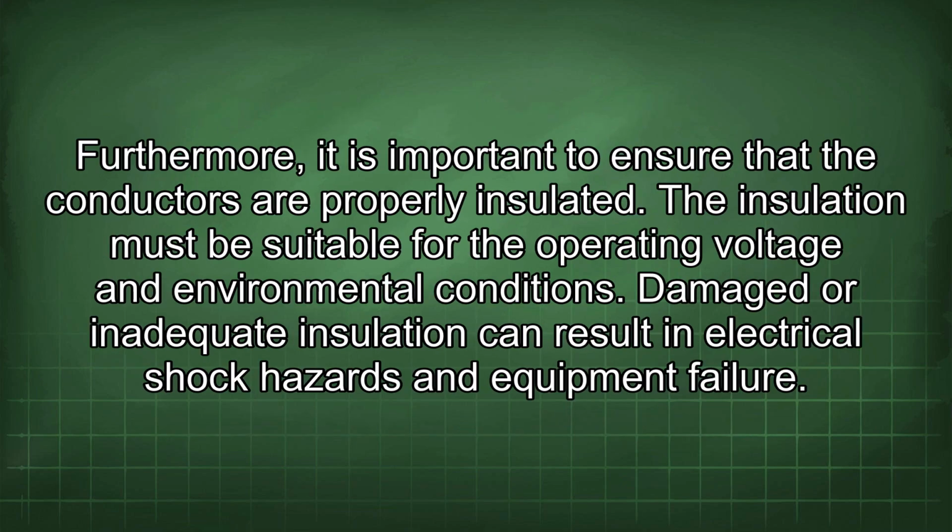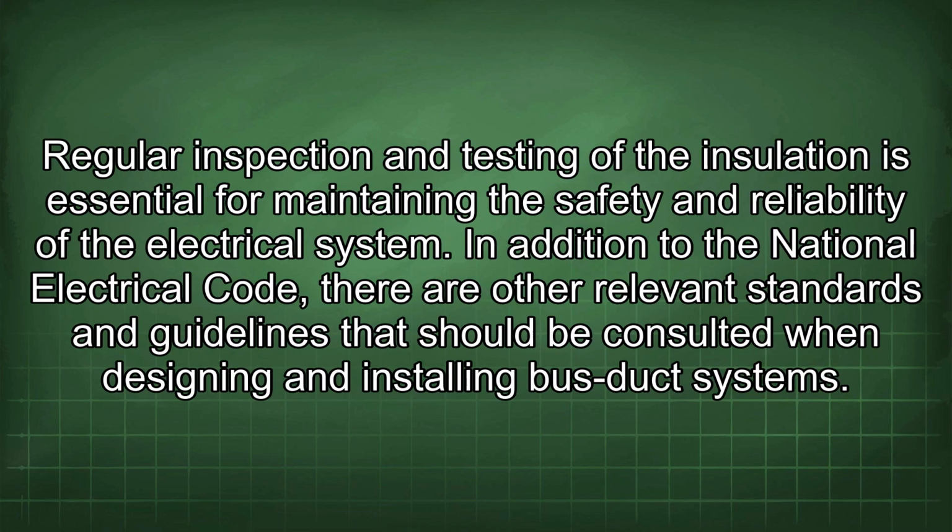Furthermore, it is important to ensure that the conductors are properly insulated. The insulation must be suitable for the operating voltage and environmental conditions. Damaged or inadequate insulation can result in electrical shock hazards and equipment failure. Regular inspection and testing of the insulation is essential for maintaining the safety and reliability of the electrical system.